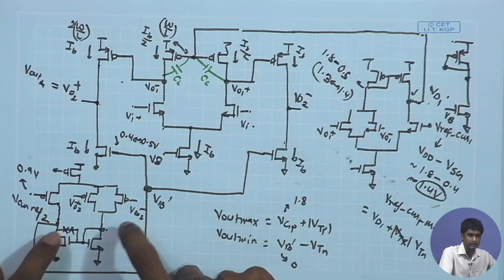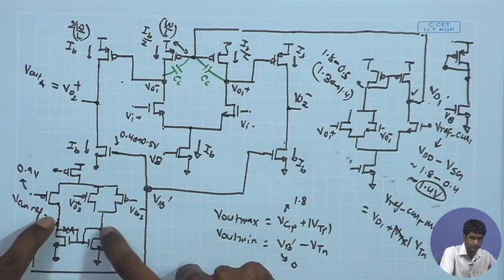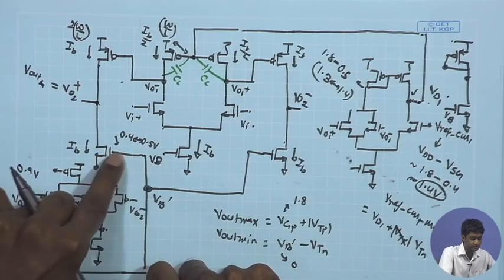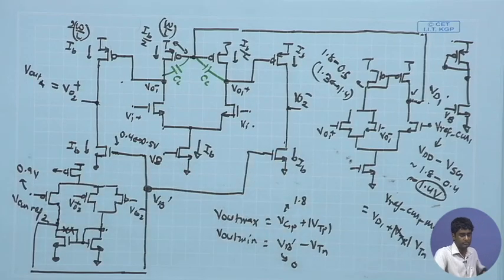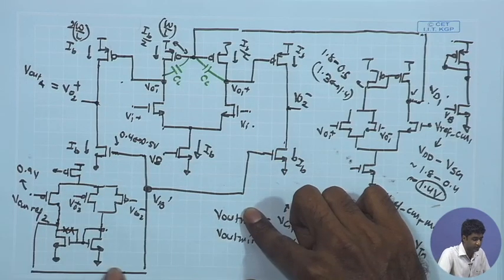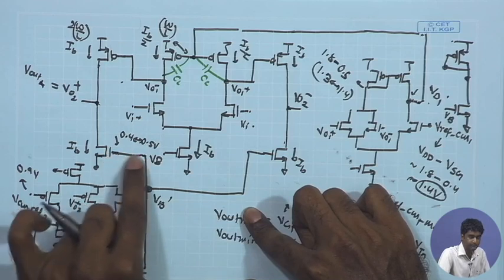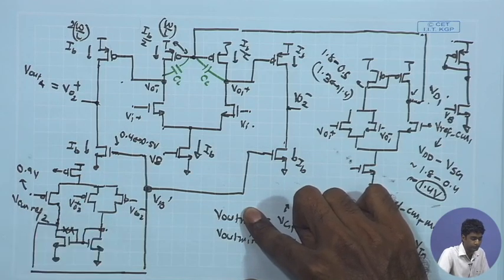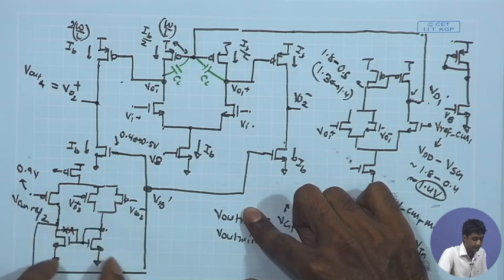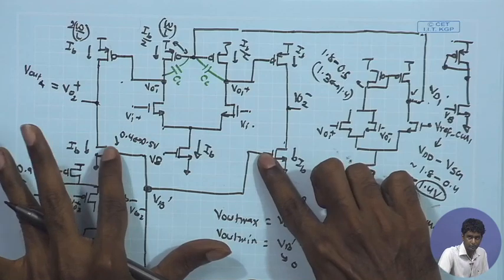Therefore, the drain potential of these two NMOS is going to be close to VGS of NMOS, which is fed to these two NMOS also. So, that is why the output DC point is naturally close to the gate potential of an NMOS. Therefore, I would like to use the error amplifier with PMOS as input device, NMOS as load to bias the current sources over here.